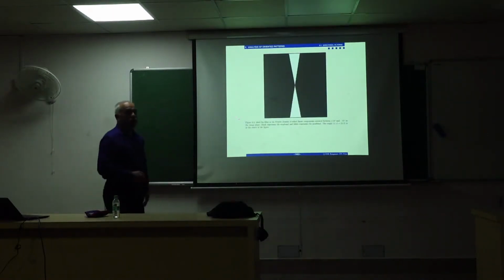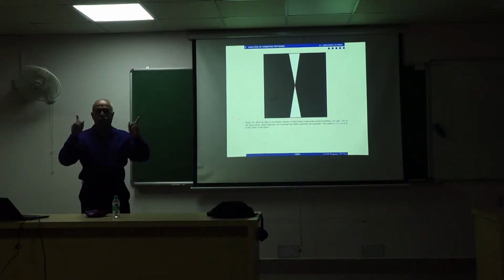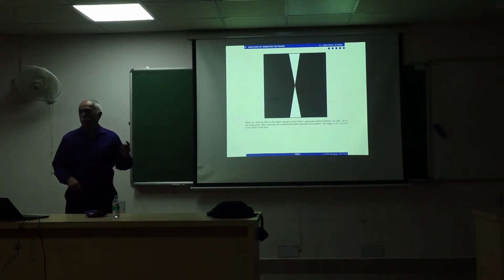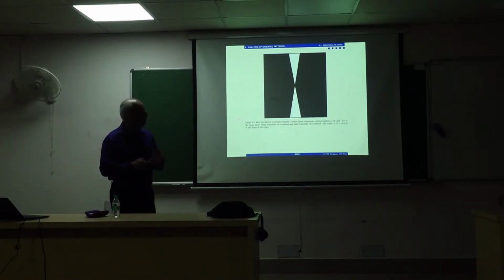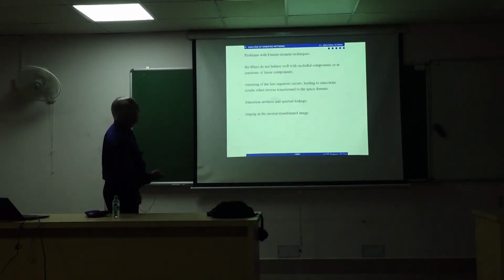So this is a fan filter in the frequency domain. This is the horizontal U axis. This is the vertical V axis. DC is here. This is called a fan, like the blades of a fan when it's not running. So there is symmetry: positive U, positive V frequency, negative V frequency, positive U frequency, negative U frequency. Okay? Symmetry in both U and V. Not isotropy. I'll skip some of this review.